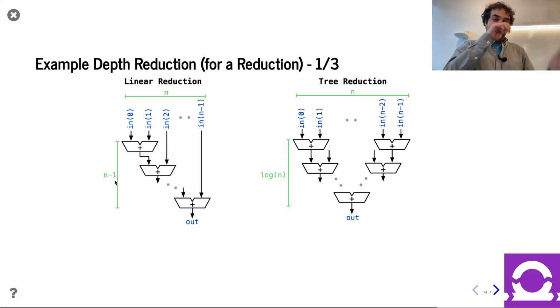So what's going on with that? Digging deeper, the semantics of Chisel and FIRRTL is such that if you have the non-truncating addition, you take the max of the 2 input widths and add 1 to it. That particular methodology is going to result in the over-provisioning of bits here. It's overkill.